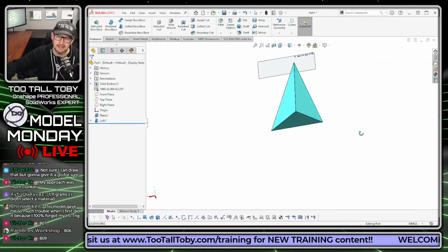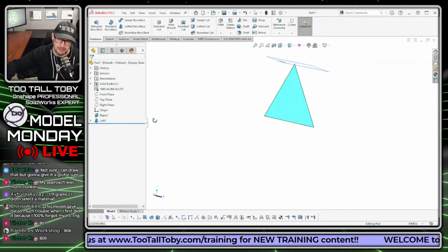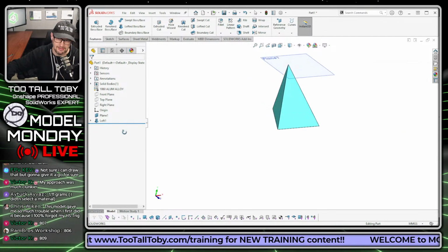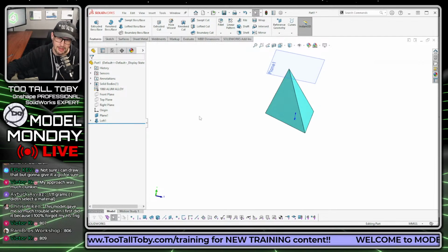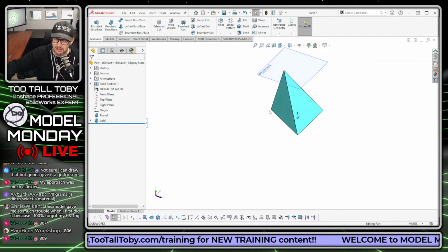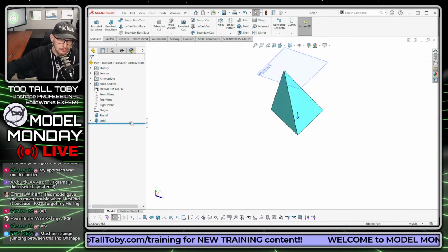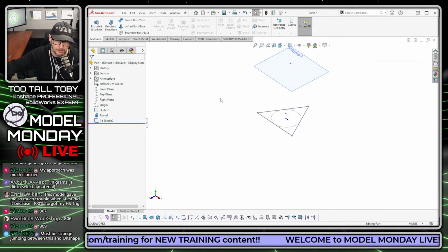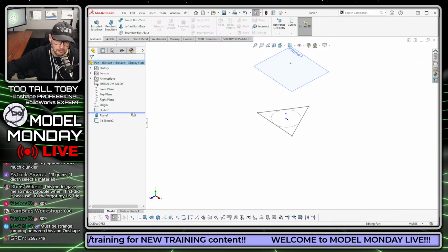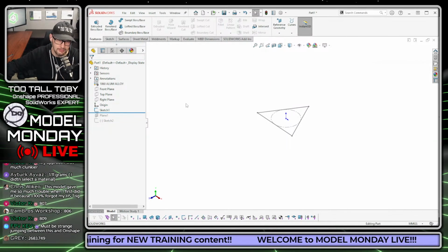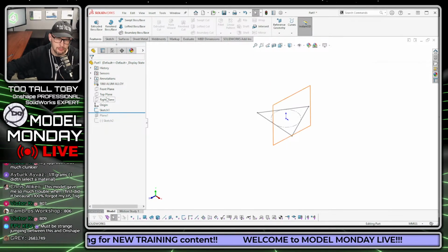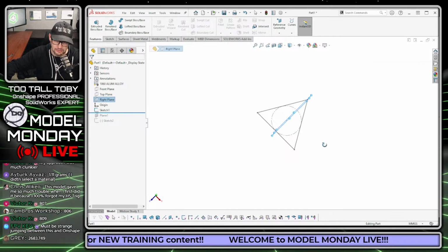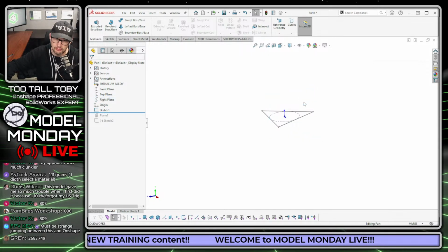So I just always like to take a moment and remind people about that, because a lot of times that's the difference. That's what's going to end up saving you the challenges that you may run into when you're trying to create this thing. So if we go back here and we go to our first sketch, let me Control Z for undo, and then I will roll back in the tree here so that we're at this point. Then maybe what we could do is take this plane, which is bisecting the triangle, and begin a new sketch on that plane.